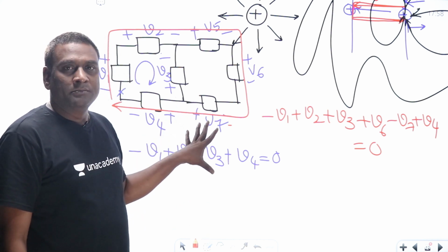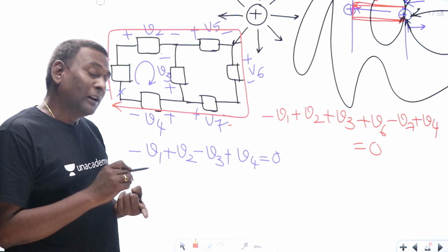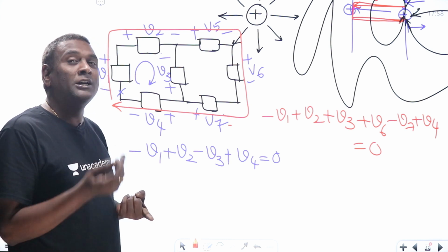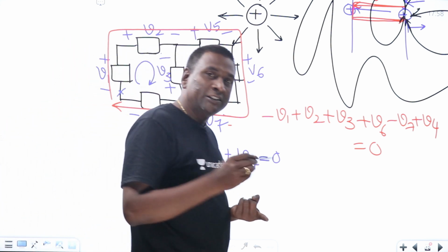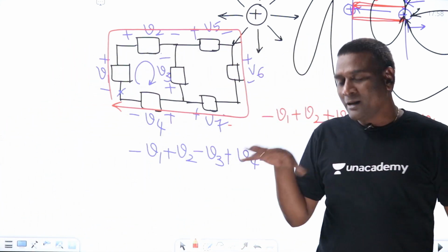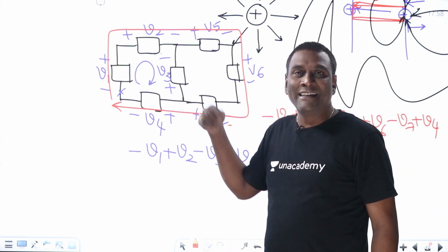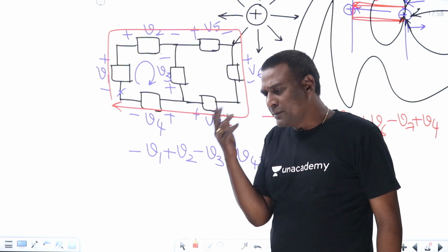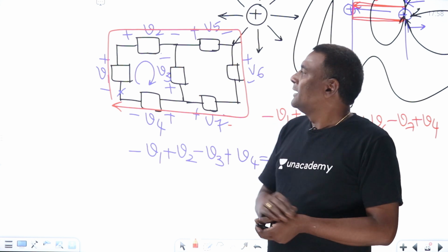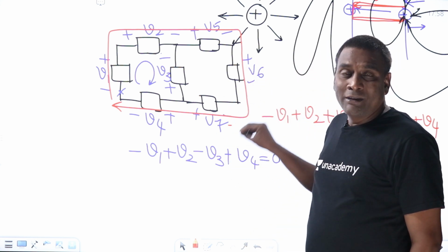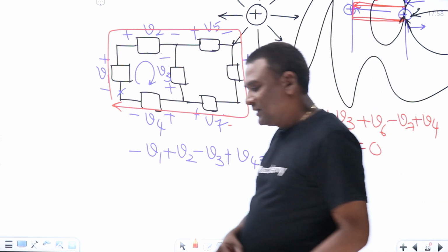And again here, can we apply KVL for linear, non-linear, lumped parameter models? Yes. But distributed parameter model is kind of an infinite system. Can we apply it there? You can apply it, because KVL is derived from conservation of energy. So for the distributed parameter model also you can apply it, but we cannot find closed paths there. Now, the moment it is derived from conservation of energy, in future some issues will come.